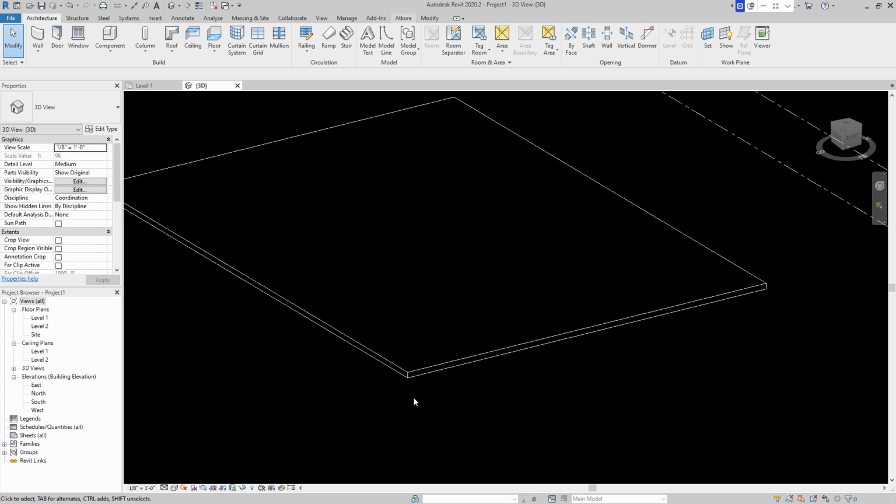If you have, for example, a CMU block wall with certain patterns, and you want the slab to be depressed, let's say 1.5 inches, to accommodate the CMU block, then you're going to have to create multiple in-place void families. So the best way to go about it would be just to generate a void family which you can bring into your project and just copy and manipulate. So let's start off and generate that void family.